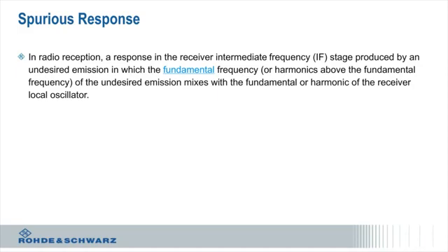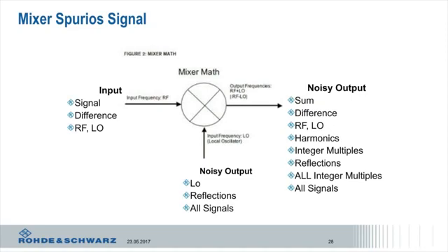A mixer is typically a 3-terminal device, and there's what we call an RF, an IF, and an LO. Usually you put in a fixed frequency at the LO, and it's used to move the frequency from the RF down to an IF, a lower frequency, or from an IF up to an RF in the case of a transmitter, but we're just talking about receivers today.